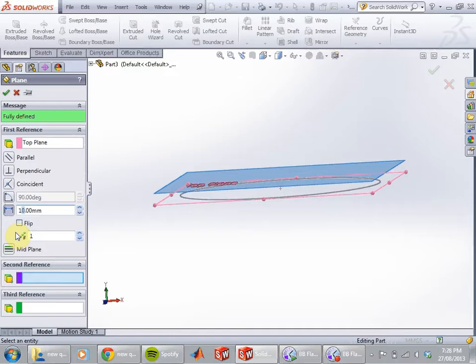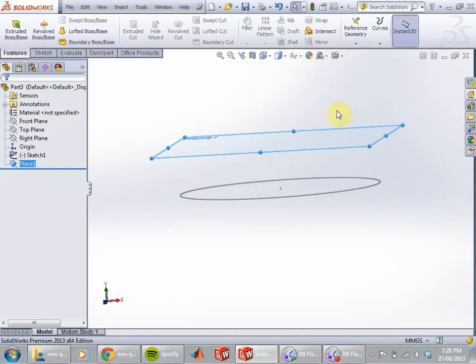So what you want to do is get the cross sections from the bottom, quarter way, halfway. And then you can make SolidWorks fill in the gaps. So you make one cross section, another one, and make it fill in the gaps. So let's go 40.